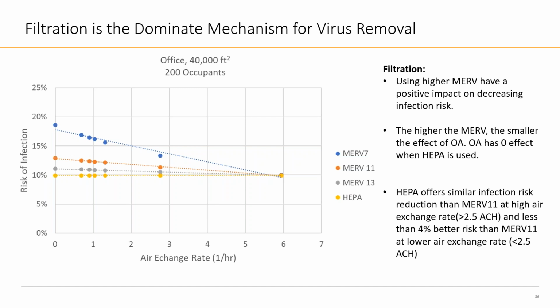I will give you an example. If you have a stadium and you want to use the indoor air quality procedure, and you have two settings of outdoor air and air cleaning, in case you have a match or you don't have a match, like you have an event or not an event, you can do that. But it can all be under the umbrella of the indoor air quality procedure. You don't need to go through the demand control ventilation.